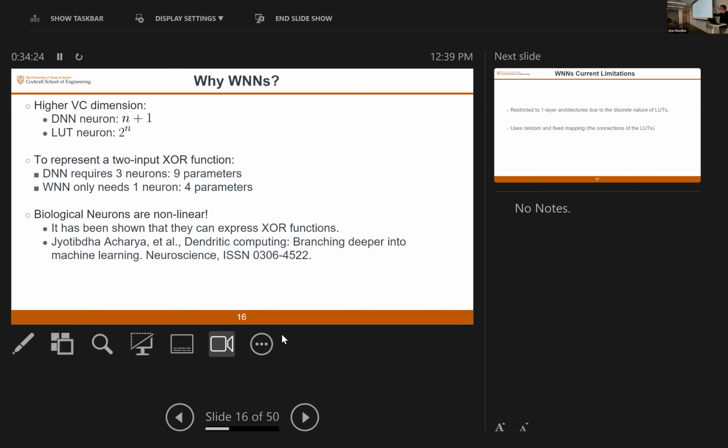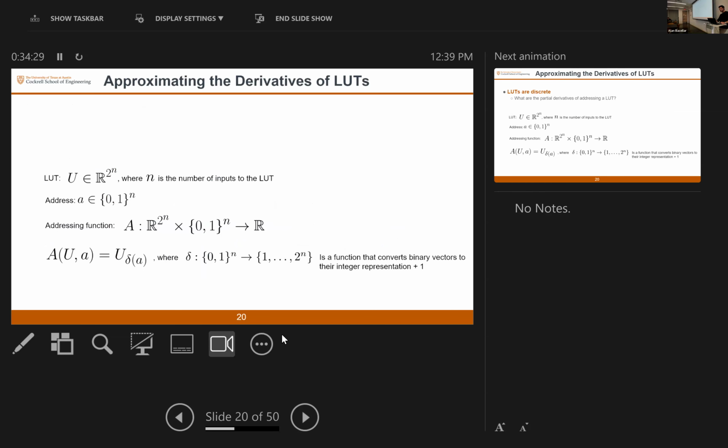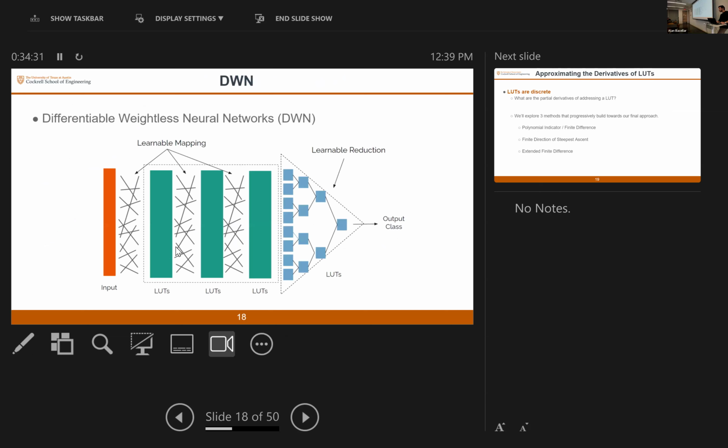It's just a collection of small sparse lookup tables, LUT2s and LUT6s. The biggest one we have used here is only 6 inputs. So this is not a huge lookup table, it's a collection of small lookup tables. So my question is, how do you encode a function? I have like 1,000 inputs. How do you break that up into lookup tables of size 6 inputs?